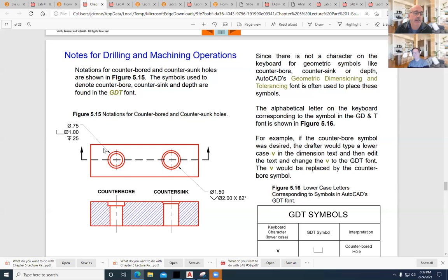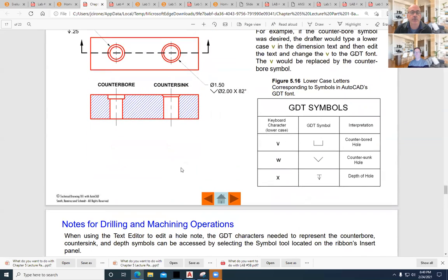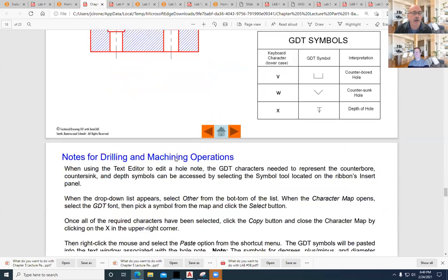As you go through and you work with things, you want to start to look at what a counterbore is and a countersink, because if you do work with it, people will expect you to kind of know those things. A counterbore is a relief for something like a washer, and a countersink is a chamfer. So you have a slotted screw, a machine screw that would fit, or a wood screw that would fit. So a lot of your fasteners will have these standardized reliefs or angular measurements. And so as you go through, pick up on that and we'll teach you how that works.